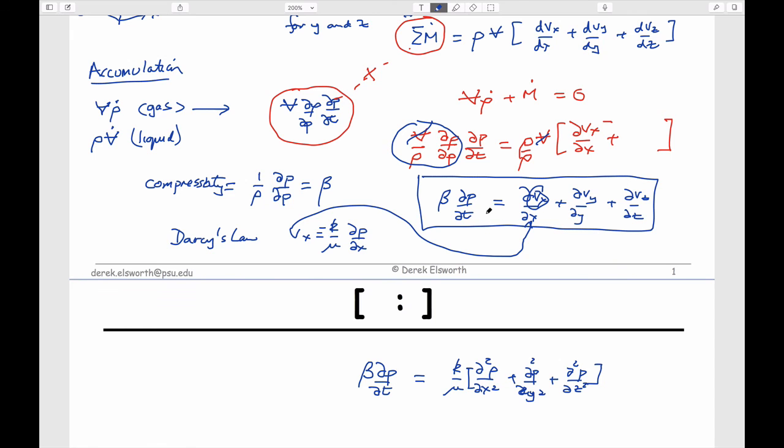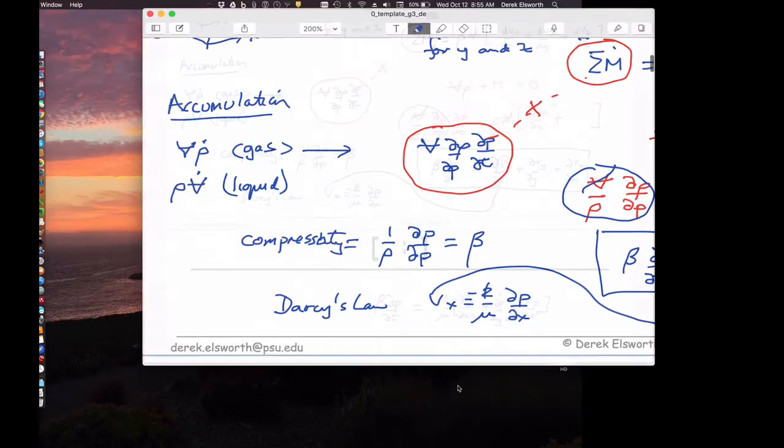What we'd like to do is write it only in terms of pressures, and the way we do that is we use Darcy's law, which accounts for an upstream pressure going to a lower downstream pressure, expending pressure as it goes downstream, which means it's got frictional losses within it. And that frictional loss is what gives this flow equation through permeability and the viscosity of the fluid, the loss within a system. We're not solving for momentum, but intrinsically we've allowed for energy losses within the system that allow us to be able to explain exactly what's going on.